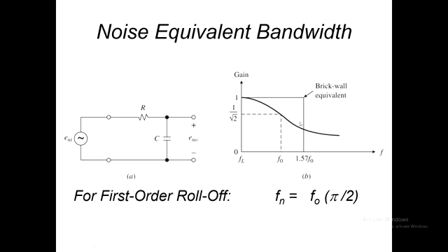And here's a low-pass filter that we're all familiar with, a first-order low-pass filter, where we'll get good transmission in the bandwidth, which is indexed by the 3 dB point, or the 0.707 value of transmission, and thereafter signals get attenuated at higher frequencies. So over here, signals are gradually becoming attenuated.